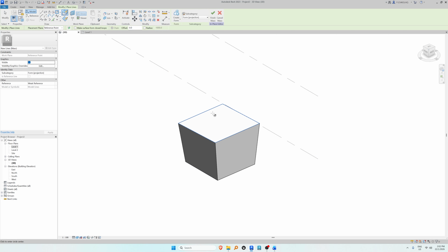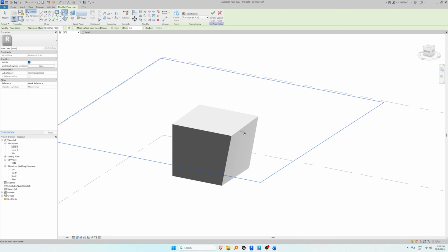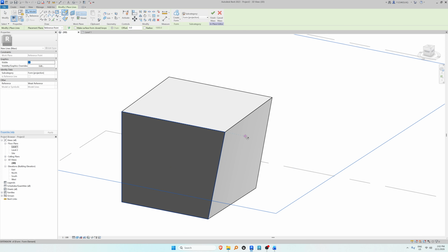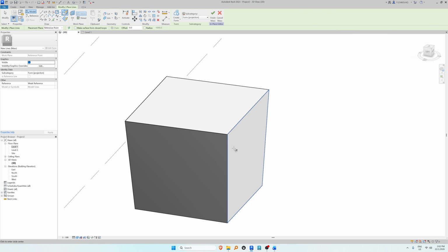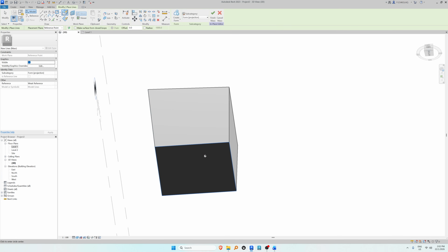We want it to be drawing on any of these surfaces, right? So if I mouse over this surface, you can see it turns blue. But for this one, because it's too slanted, Revit is not allowing me. It's picking this one, the top one. This one also cannot, but the base one should be fine because we didn't modify it too much.